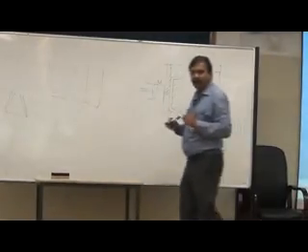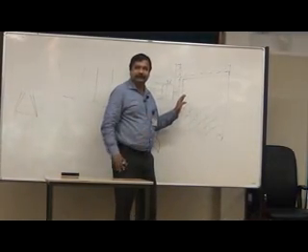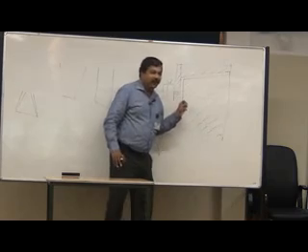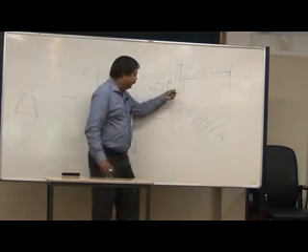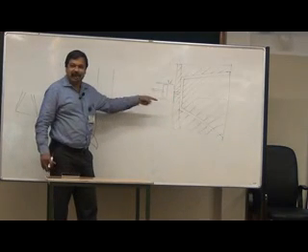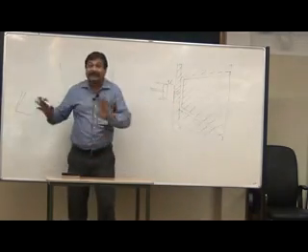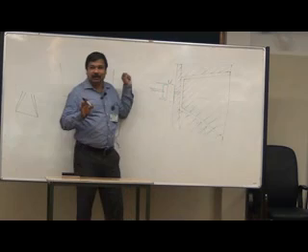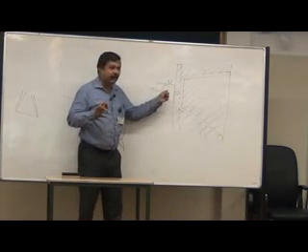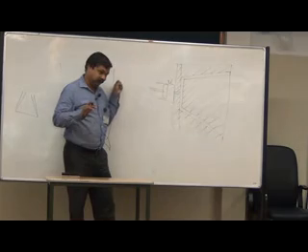Now I can very easily pull it out like this if the shape is like this. Are you able to appreciate? If the shape is like this, then I don't say it cannot be manufactured, but the solidified component cannot be taken out like this.